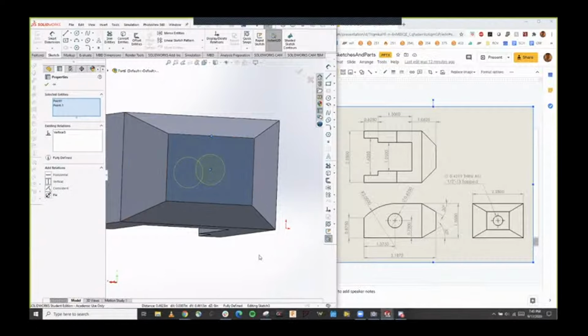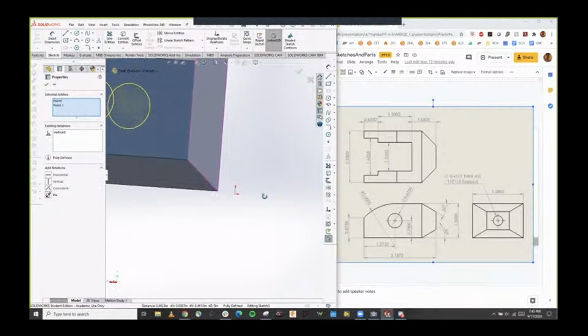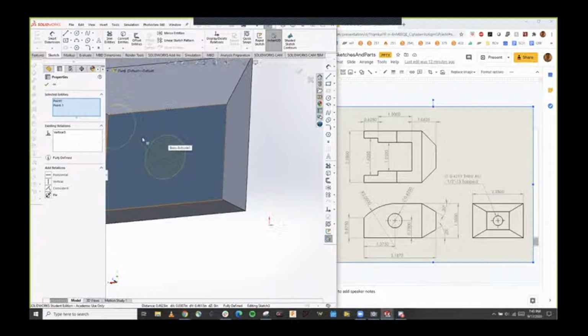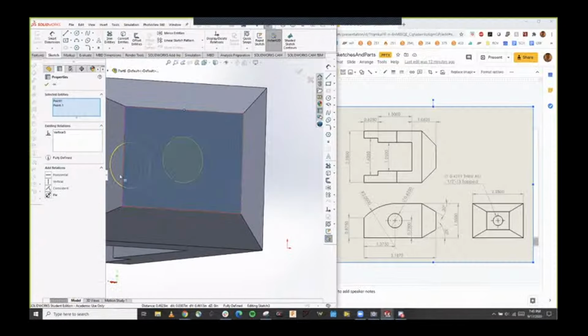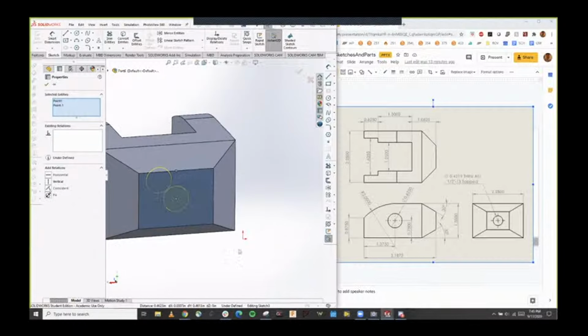The way that I can tell is because every sketch has a coordinate system like this. Remember in the beginning of this session, we talked about how to make a sketch, you need a coordinate system in 2D, and you need a plane. So where you need to be careful is when you're doing some of these dimensions, if you're in a different coordinate system than your 3D part, you need to be aware of that. So for this one, our Y and our X are in the same direction, they're collinear, but the X is actually negative X. This doesn't make a difference for stuff like this.